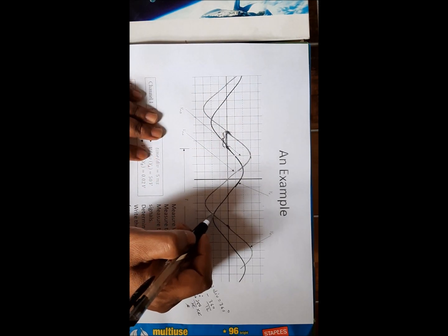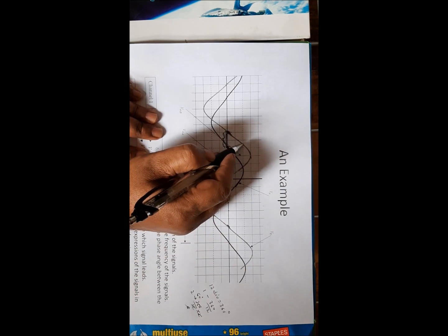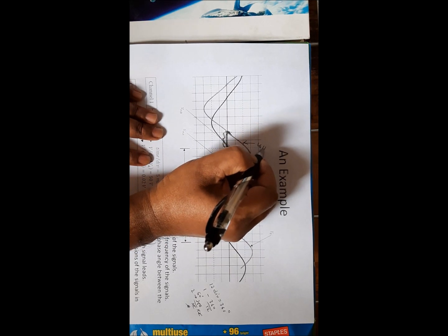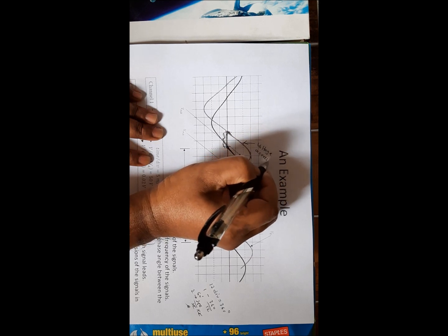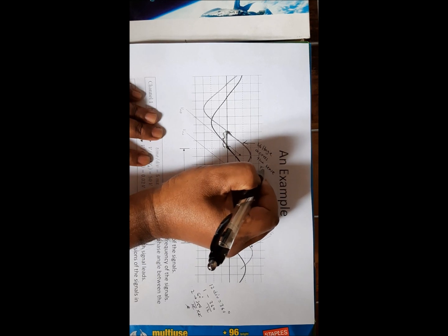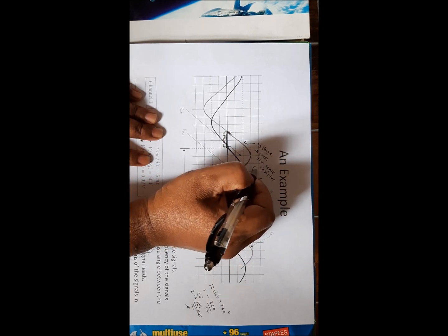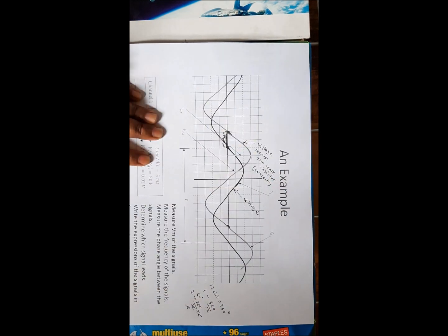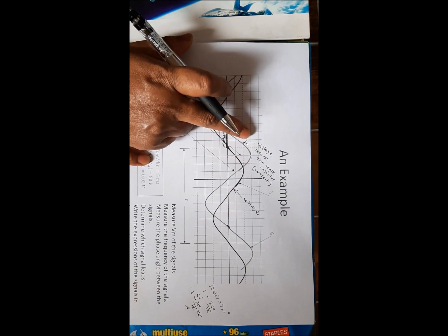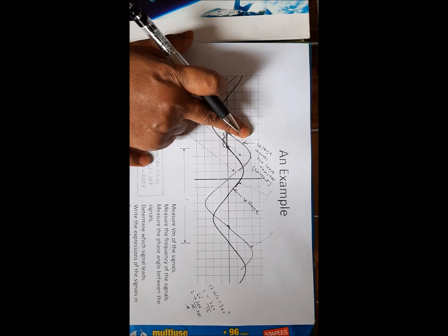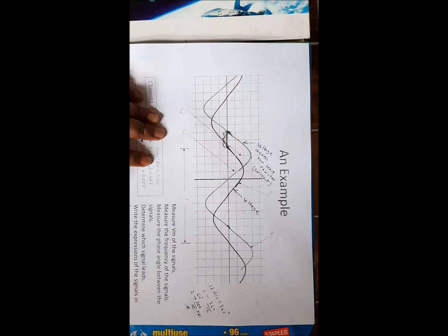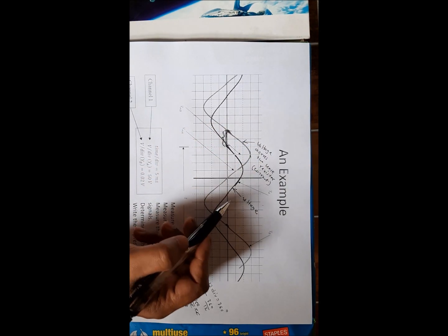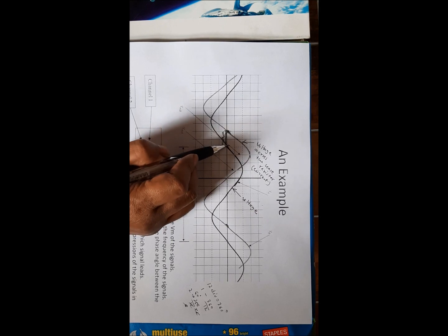Now if channel 2 is a voltage and channel 1 is a current, then current is lagging. Let's assume this is the voltage across the sense resistor, meaning that this is basically current and this is voltage. The voltage across the sense resistor is assumed as the current, because the voltage and current across the same sense resistor will be in phase. So we can say this is my current wave shape and this is the voltage wave shape, and here the current wave shape is led by the voltage by 60 degrees.